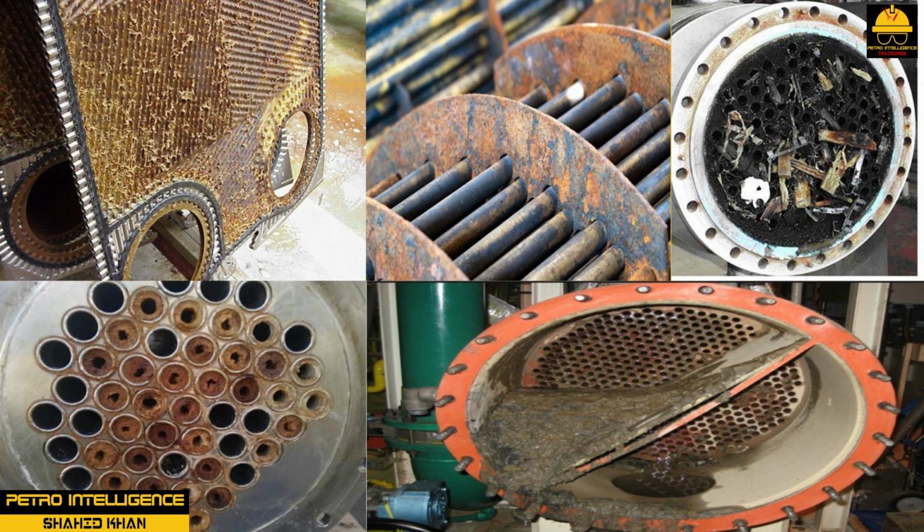Other problems associated with heat exchangers include internal or external tube leaks, gasket leaks, tube sheet leakage, damaged or crushed tubes, air-cooled fins that are crushed or fouled, decreased flows due to poor pump performance, sheared tubes, or air trapped in the shell. A heat exchanger's effectiveness is typically linked to three things. First, flow rate of each process stream. Second, temperature differences between the two opposing streams. And third, the cross-sectional area of the heat exchanger.